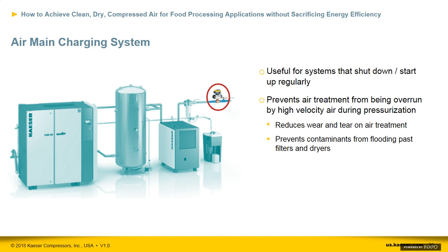If the demand of the system exceeds the capacity of the compressors, the pressure would drop, and then you're overrunning your air treatment. Finally, that same valve can also be used to close off the compressed air supply in case there are any alarms of the air treatment components, like the drains, the dryers, or any additional alarms. A good choice would also be to add a pressure dew point alarm for your most critical applications.